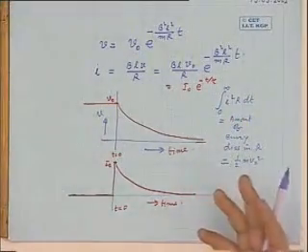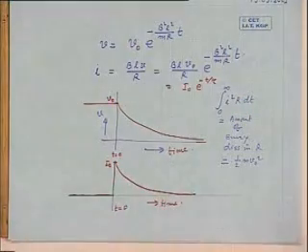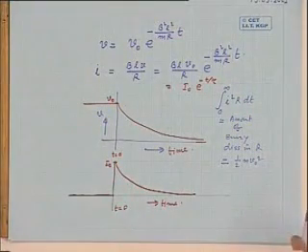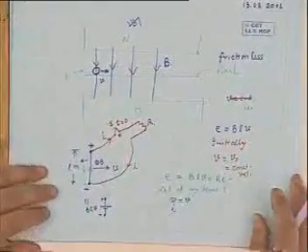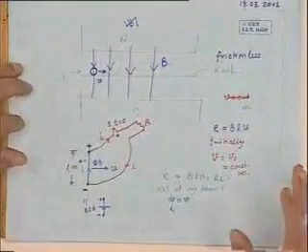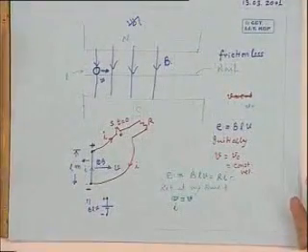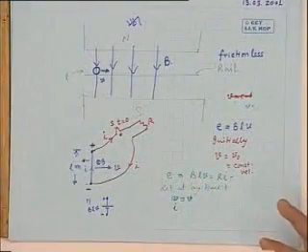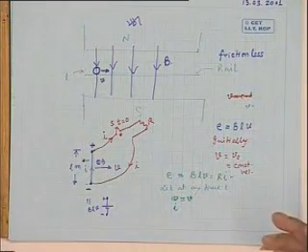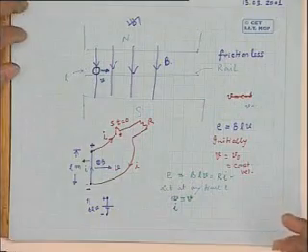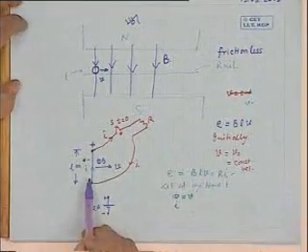You can easily show that. So the initial kinetic energy, whatever was stored, will come to 0. Therefore, a generator without a prime mover will ultimately come to a stop. So long as its kinetic energy is there, it will be able to supply energy, and that too not at constant voltage like that. Current value decreases like that.